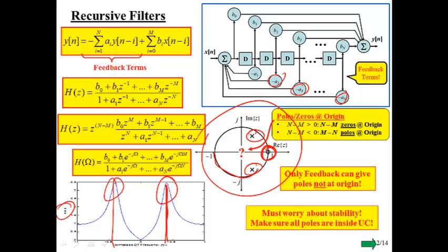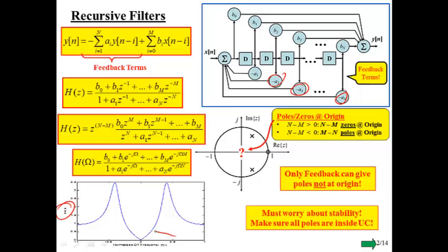That's at an angle of 0, and so that's a discrete time frequency of 0. And you'll notice that the frequency response is pegged down to 0 at that particular frequency. So again, it's important to keep in your mind that this discrete time frequency omega is tied to the angle around the unit circle. Remember that Burger King crown that we unfolded.